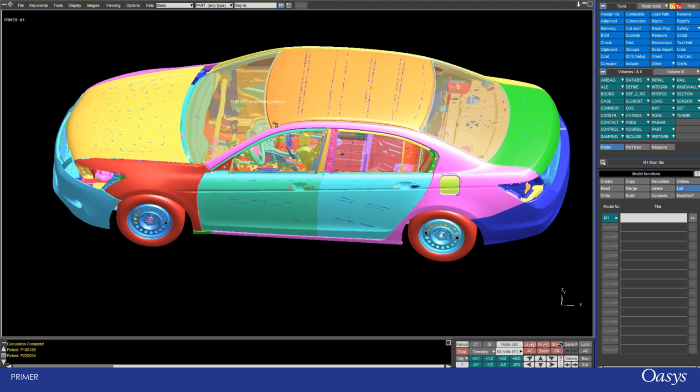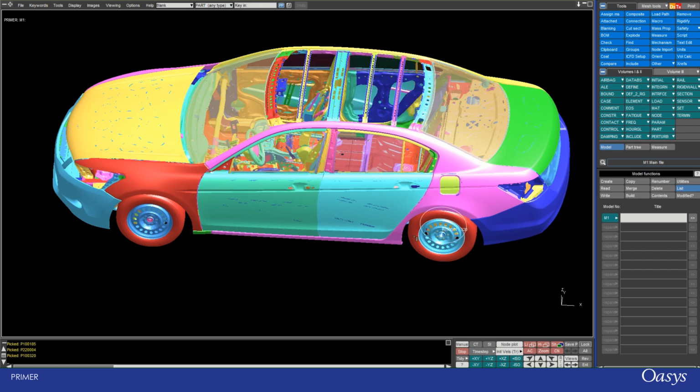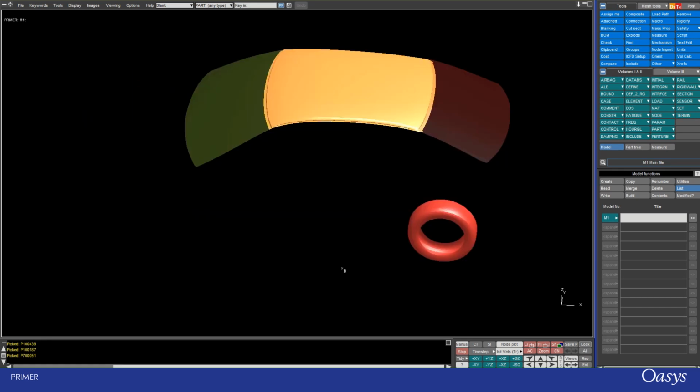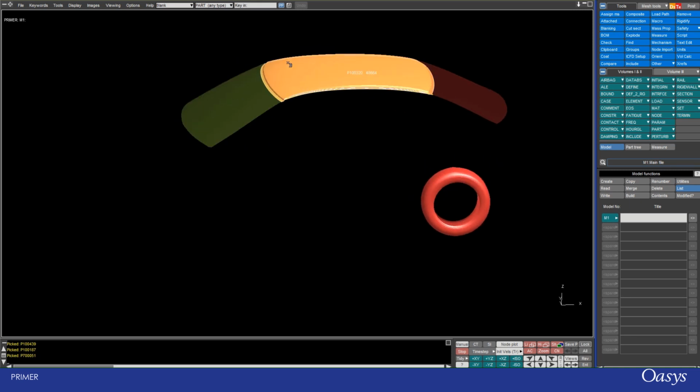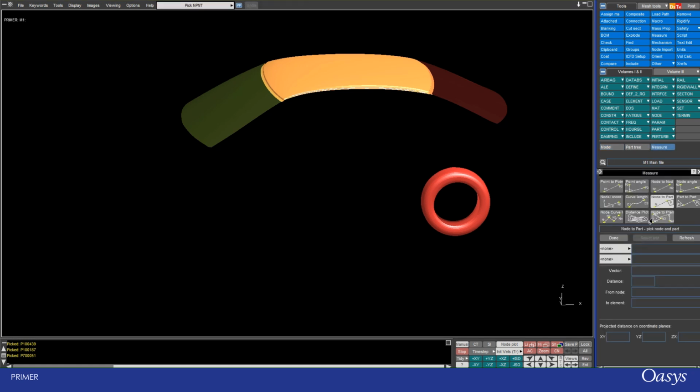So we can blank. I'm just going to blank maybe the roof, these two windshields, and how about a wheel? And then if I click the R button on my keyboard, that actually reverses my blankings. So now only the things I blanked are visible. Looks a bit strange, but this will be useful for displaying the rest of the options we have.